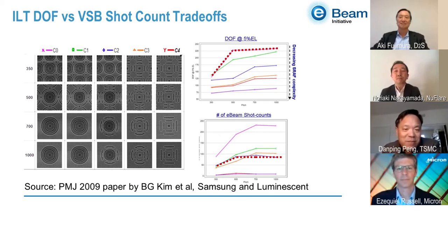So it's simplified to about 4 rules: minimal CD, minimal space, minimal island, minimal holes. And then we also do not want to see kinks and bumps on the shapes, which even a multiple beam mask writer cannot resolve.